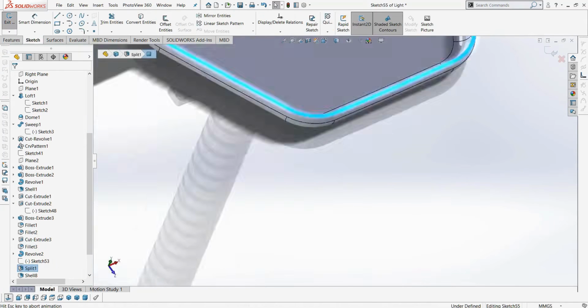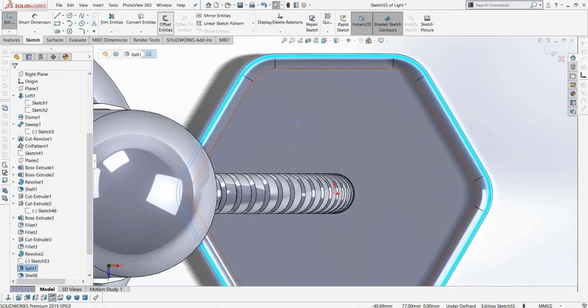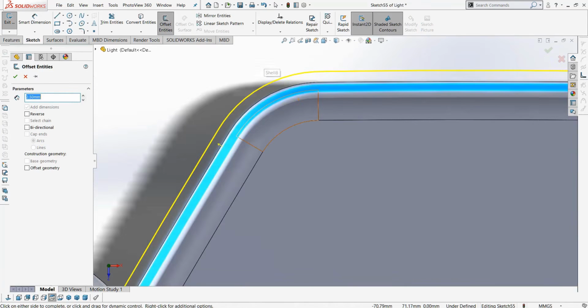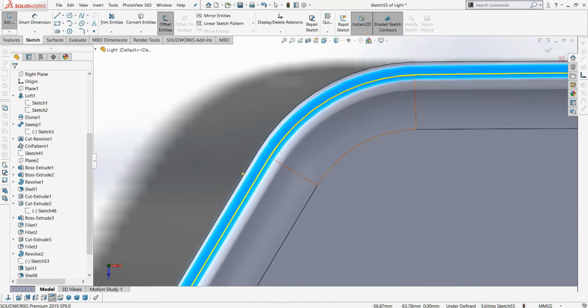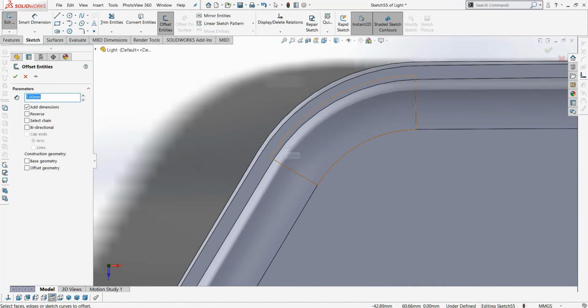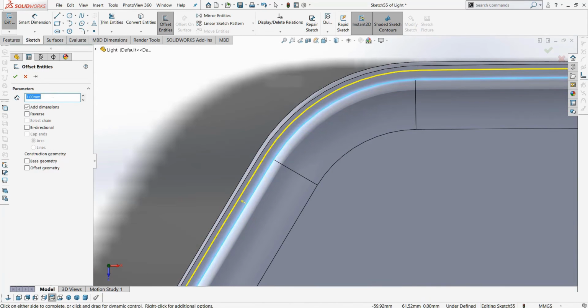Now I will select the edge and say I want to create a sketch. The sketch I want to draw will be offset by this amount. I will apply the offset again and select this line exactly. Let's set the size to 7500. I think half of it should be fine. I want to extrude cut something like this, going down by 1 millimeter.